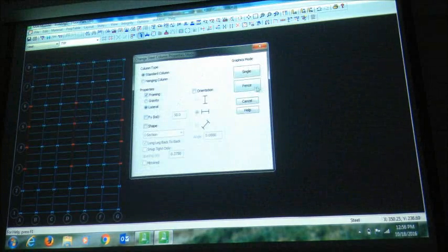Okay. Now in this direction I will add some braced frames. How about that? In this direction, braced frames are also my lateral system, so I will change the columns to lateral, maybe 2 bays, 2 bays, 2 bays, 2 bays.